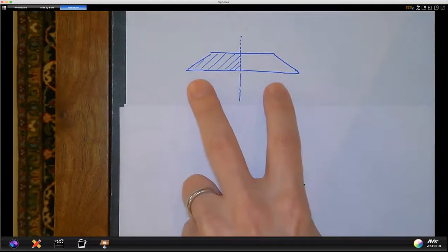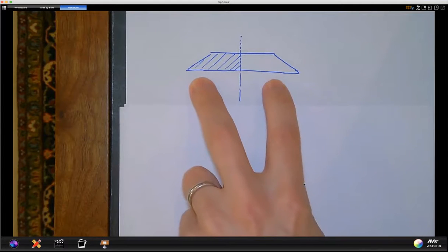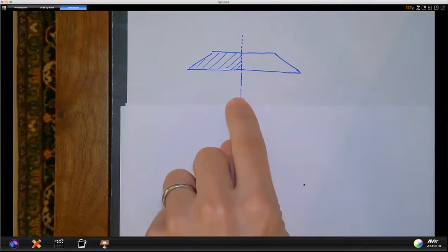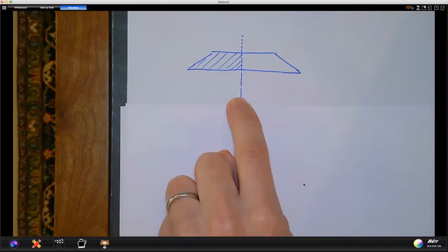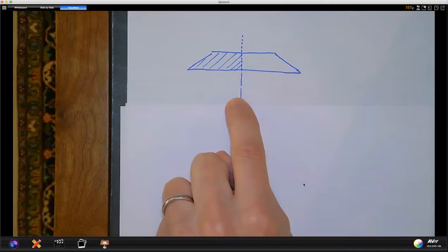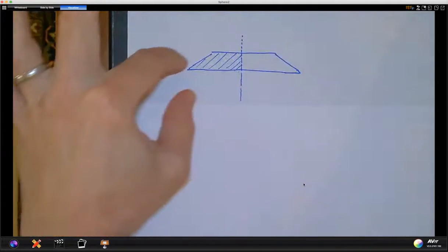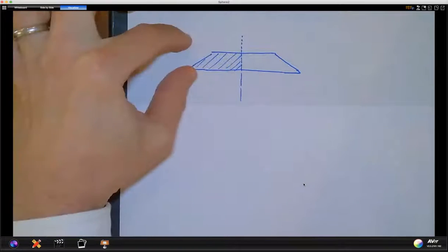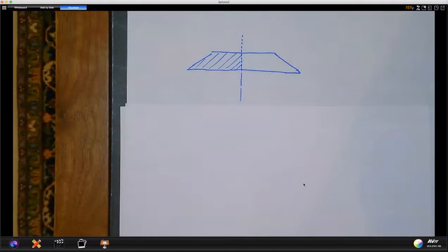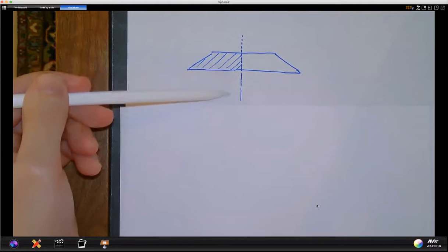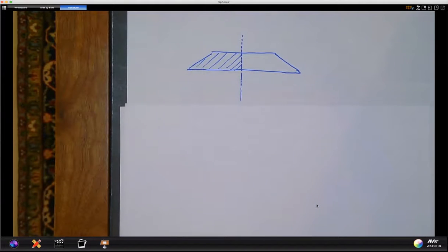And if this is indeed a big embankment, and A and B are in fact large, having a point right down here under the middle should result in an influence factor of 1.0 or close to that, because what is happening is this is acting simply like another soil layer on top that doesn't even have influence factor associated with it. It is just an entire new layer being the same distribution, same stress all the way with depth, so not even being distributed at all.